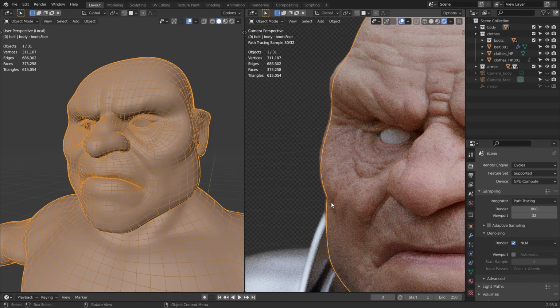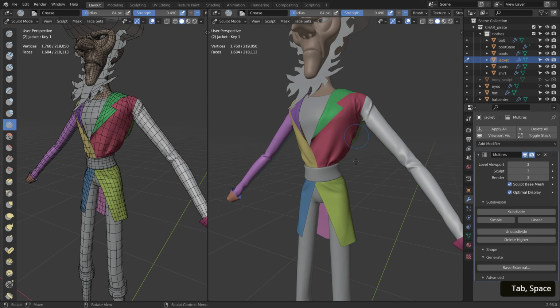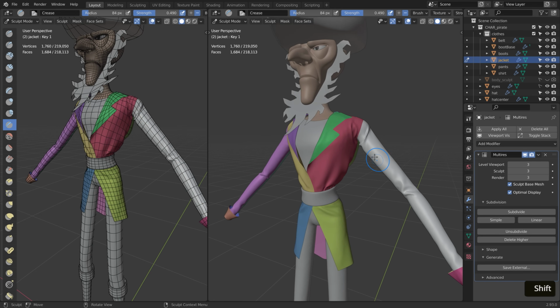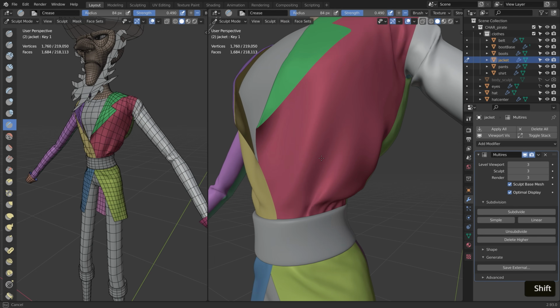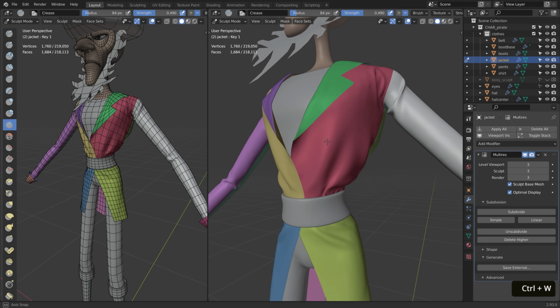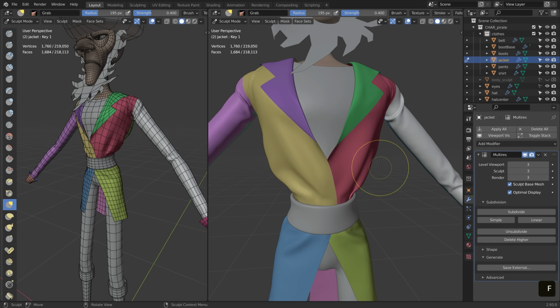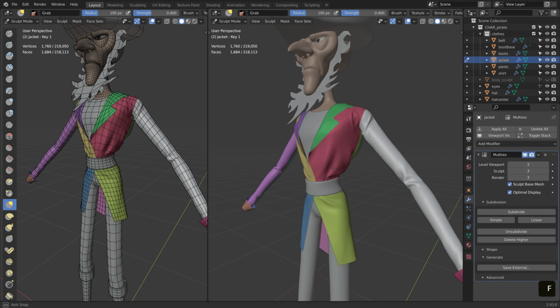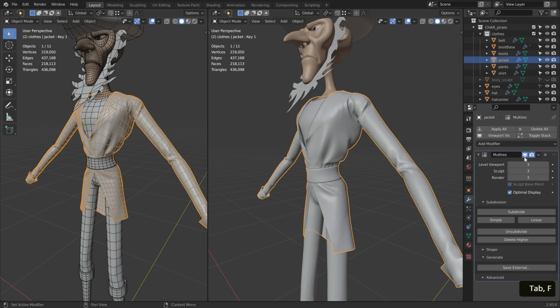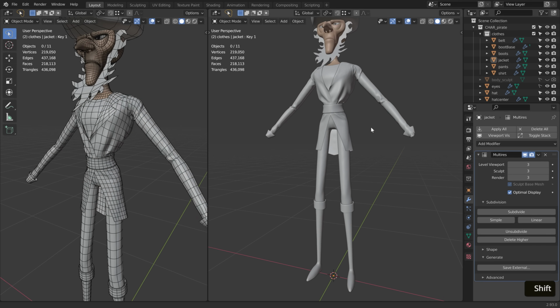If you're doing the high poly sculpt in Blender, then technically you can skip this step and use the multi-resolution modifier instead, which has nothing to do with texture resolution. But if you were doing something for a client, or if you're planning to use the model elsewhere, then you are definitely going to need this in order to bake everything and transfer all the necessary details along the model to the client or to the other software.